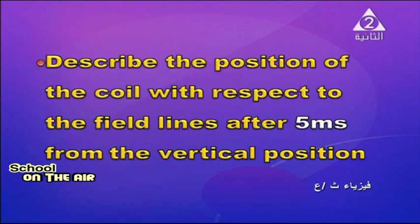Describe the position. This is a very interesting and intelligent question. Describe the position of the coil with respect to the field lines after 5 milliseconds from the vertical position. We are starting from the vertical position, so the instantaneous EMF will be equal to EMF maximum times sine of the angle.